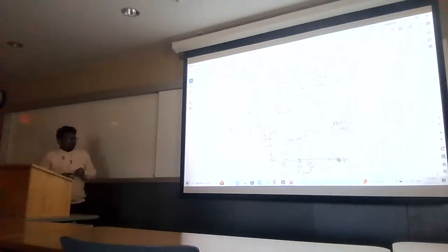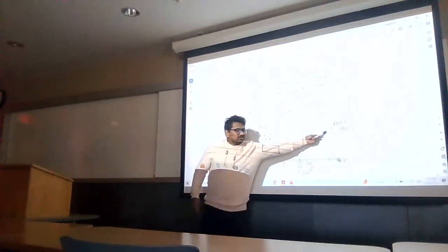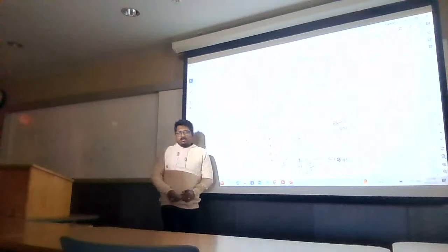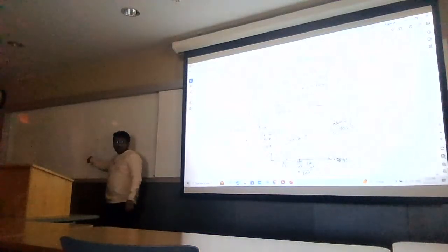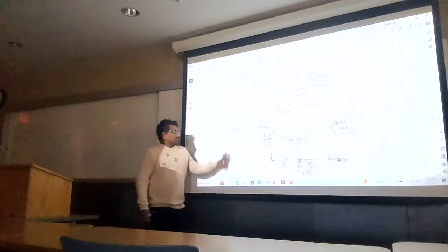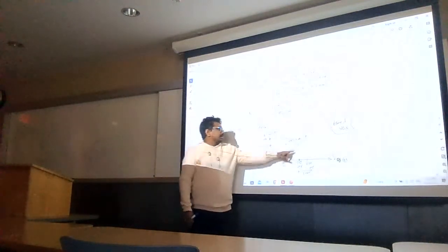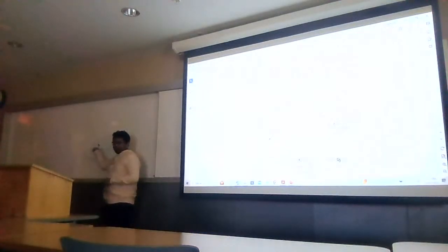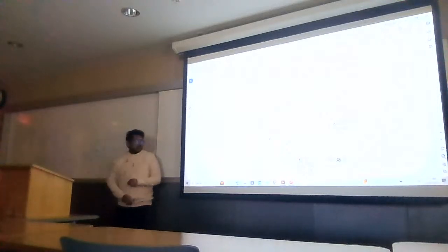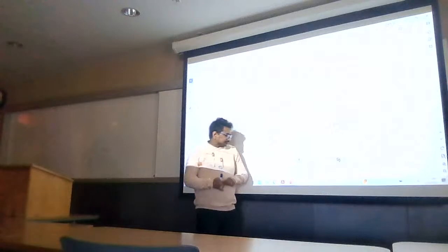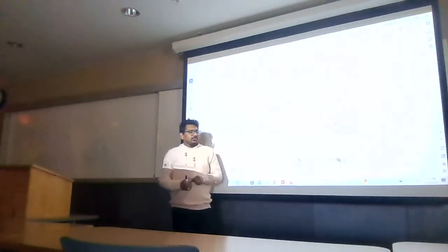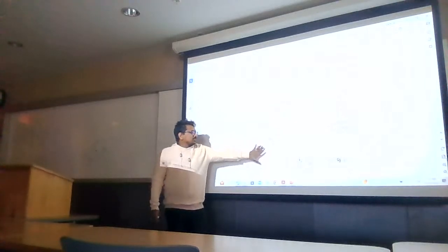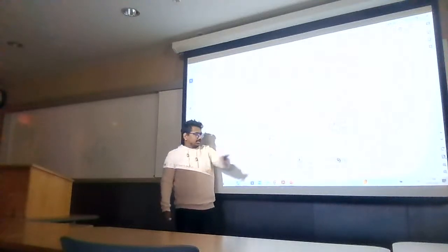In this curve you can see my VDS, my drain to source voltage, is fixed. If my drain to source voltage is fixed, and I increase this VGS gradually, then if you simulate it in any software, you will find a curve like this. This current is my drain current, the terminal current from this drain, shown like this. In an interview, you will definitely expect that they will ask about this curve and what the meaning of this curve is. There is a specific meaning.